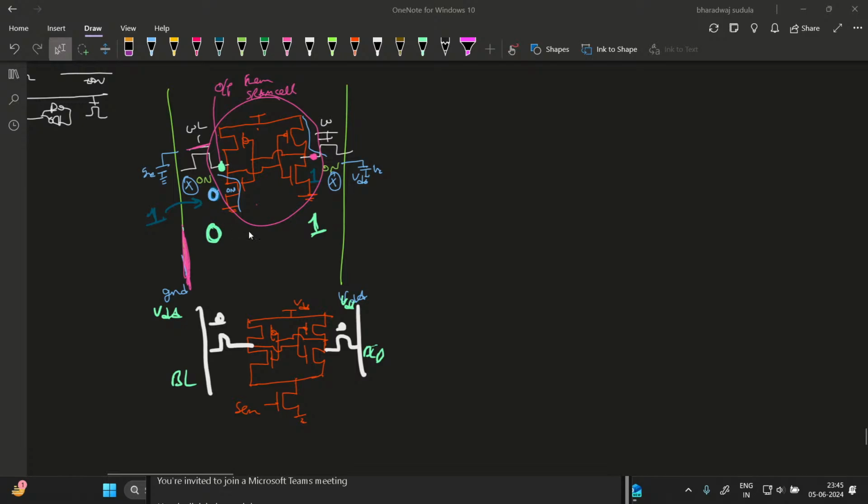So yeah, there is 0 and 1, and you precharge these bit lines to VDD, and you turn on this word line. And usually these two control pins are the same. So this bit line is connected to this node, and this bit line is connected to this node, and you have 0 here, connected to this node via PMOS, and here you have 1, connected via this PMOS.